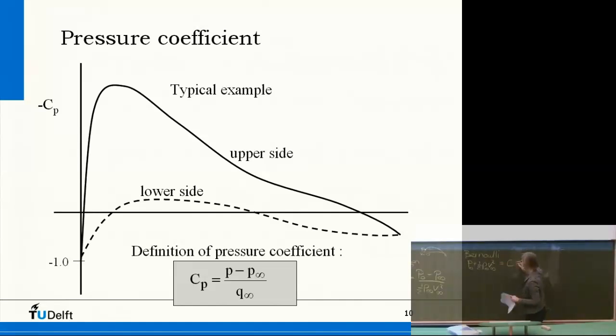And it's equal to the stagnation point on the other side, P0 plus half rho V0 squared. Well, V0 is 0. So I see that P0 is equal to P infinite plus half rho V squared. So I can take the P infinite to the other side. So I have P0 minus P infinite is equal to half rho V squared.